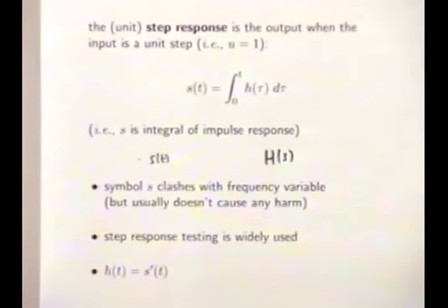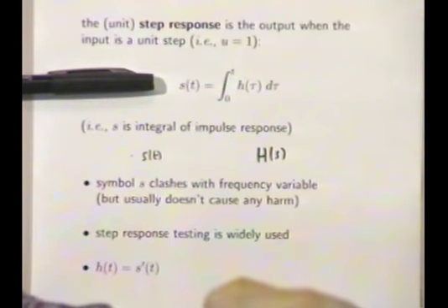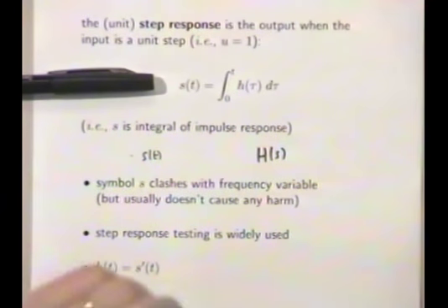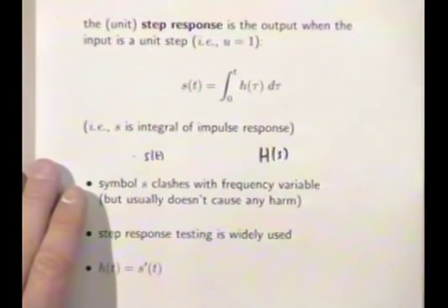There are a lot of electrical systems where a voltage will swing from 0 to some value, or a current will swing from 0 to some value. And then it just takes a while for the system to react. There's many systems where this is the case. So step response is pretty common. It's very common in chemical engineering to look at step response. Step response refers to, for example, what would happen to the pH in some solution if you turn on a pump that pumps some chemical into a reactor tank and let it keep pumping. Then the step response is what you're going to see, the step response from that reactant flow rate to the pH, for example. So it's pretty common.